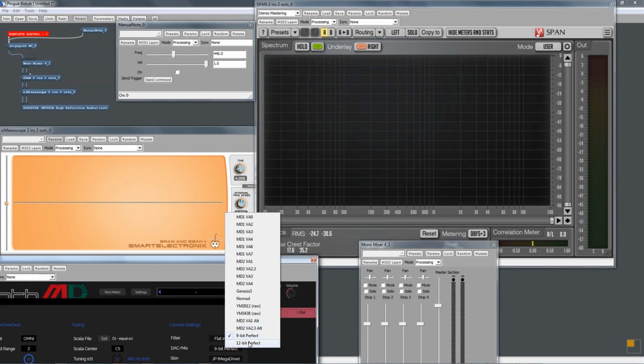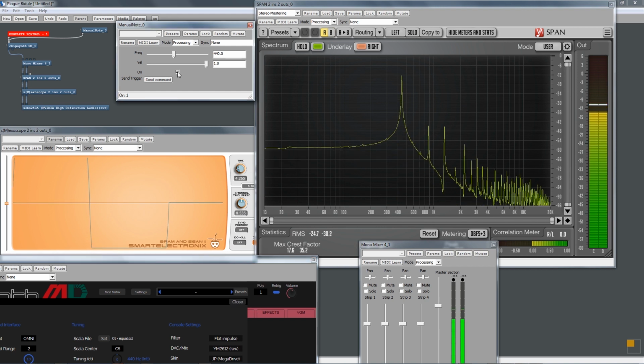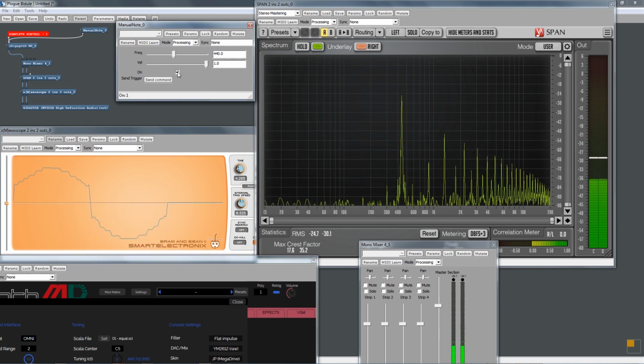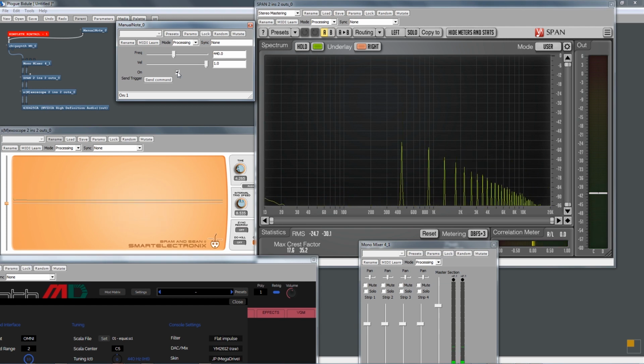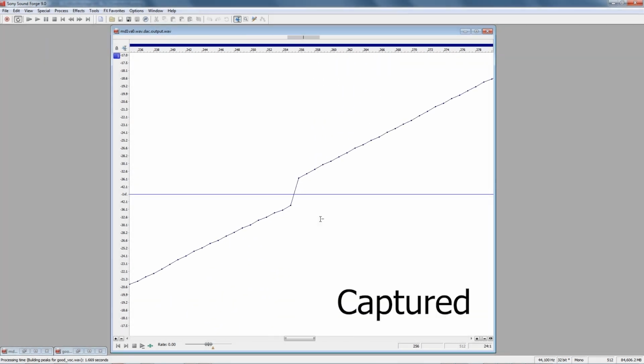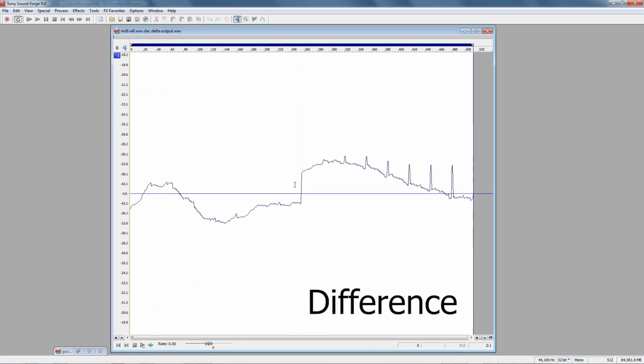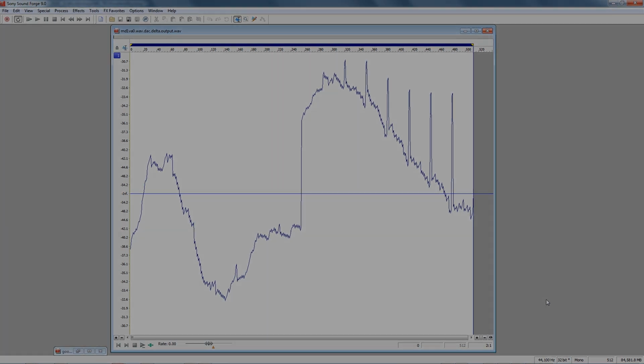The quieter the level, the less discrete values it can use. But on early models of the Mega Drive, it sounds more like this. What? Due to the way the DAC is implemented on the die, there's a huge DC voltage jump in the output when switching from index value -1 and 0, or 7F and 80 in hexadecimal.